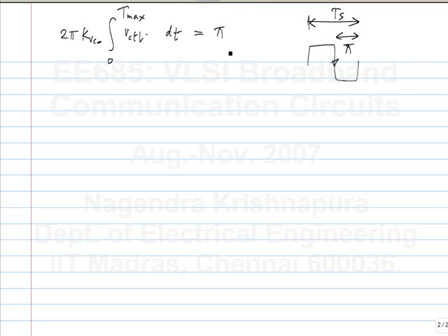Okay, so now it could be that this control voltage is in error by a certain amount. Okay, so actually what you want is the excess phase, right? So let me rewrite this. The total phase of the VCO is 2 pi f naught t, this is due to the free running frequency, plus 2 pi k VCO times V control DC.